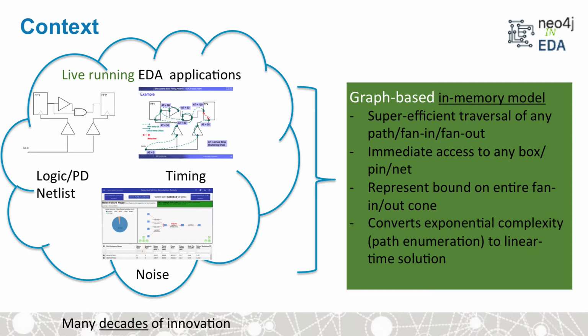In fact, in the really specialized field I work in, which is timing analysis, it's a well-known fact that we can characterize the circuit performance, the timing characteristics of any path that goes through any circuit in the design with a single number. That, my friends, is how we can tackle 5 billion transistors, analyze the performance thereof in any kind of reasonable turnaround time. Okay, next chart, please.